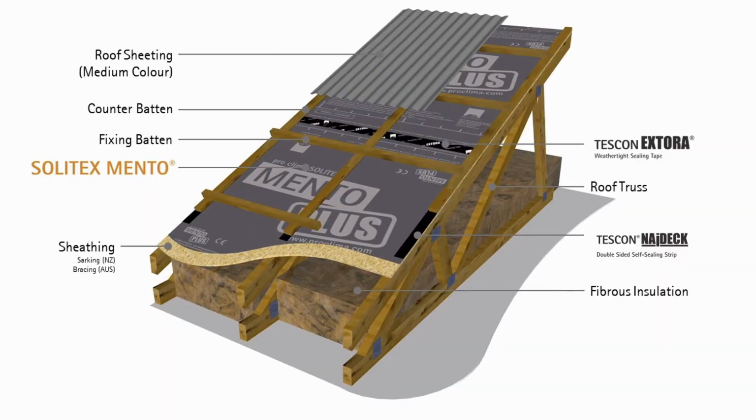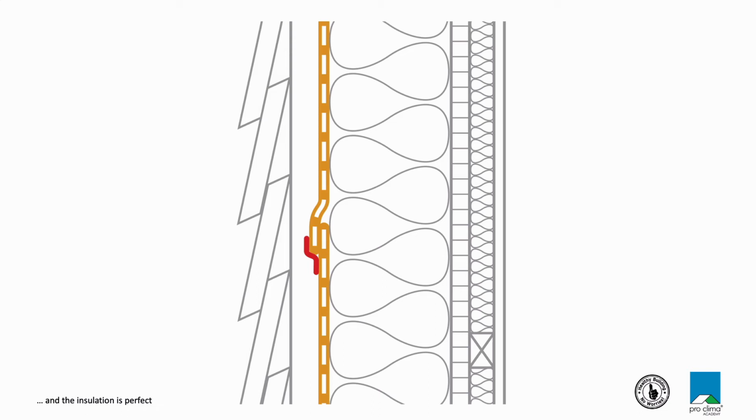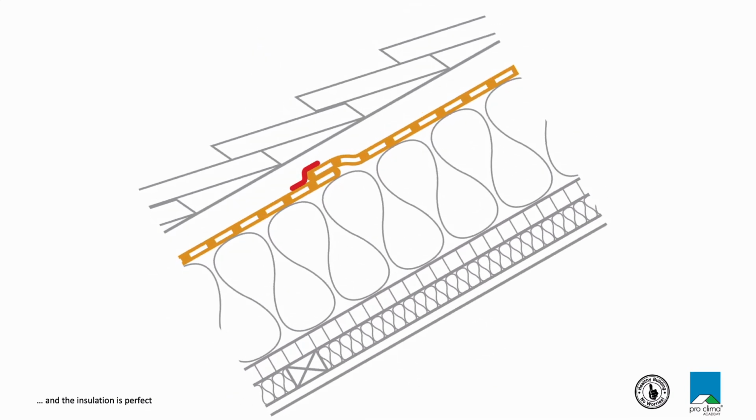And this is what it might look like on a truss roof. It's exactly the same concept. In this case, there's a rigid sheathing underneath the weather-resistant barrier of the membrane, which we would definitely encourage for lower slope roofs, but may not be necessary on higher pitch roofs. And as I said, it's very familiar to most of us. It's simply a wall construction tilted on an angle, and it becomes a roof.